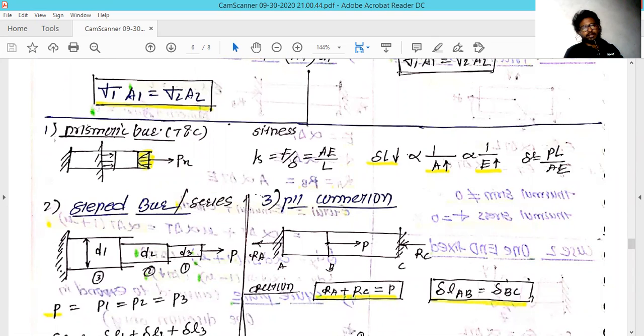When you apply a tensile force on the rod, it shows a parabolic stress distribution. If you apply the tension force at the center of that rod, the stress and strain developed at the center will be maximum, and it reduces in the outward direction. So it will not be the same, but we have assumed that the total strain produced in the entire rod is the same, whereas in actual conditions it is not the same, because it varies from the center to the radius.